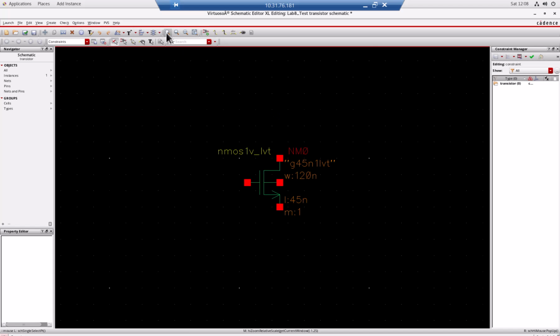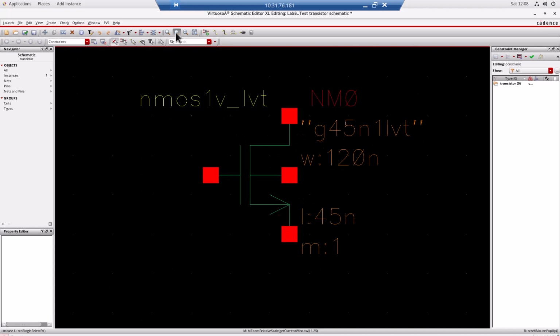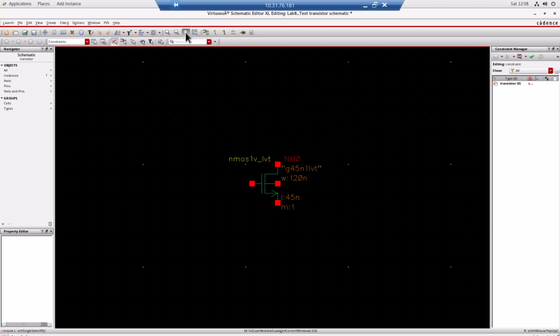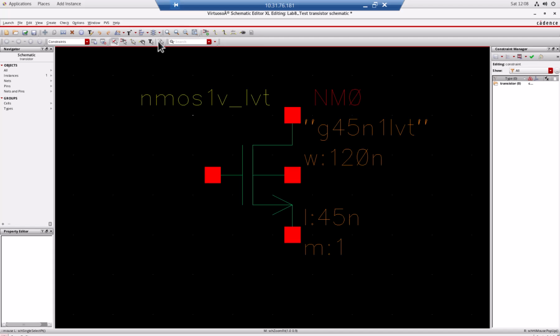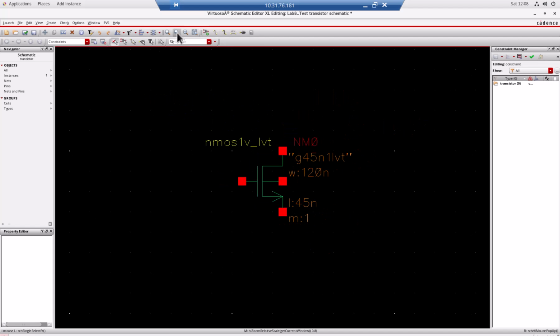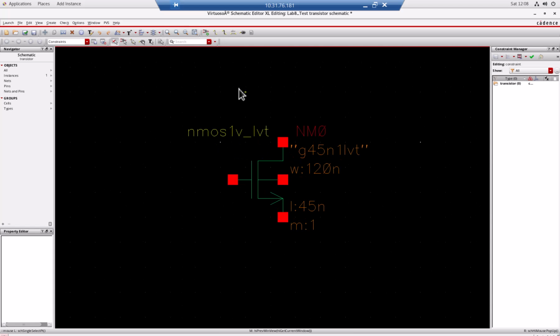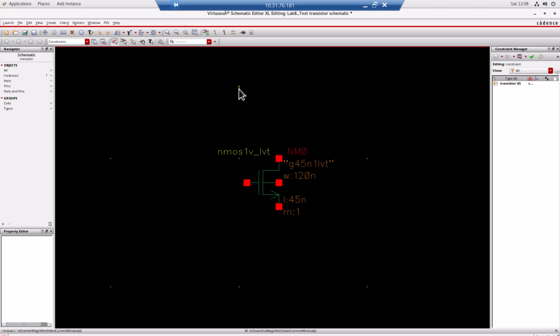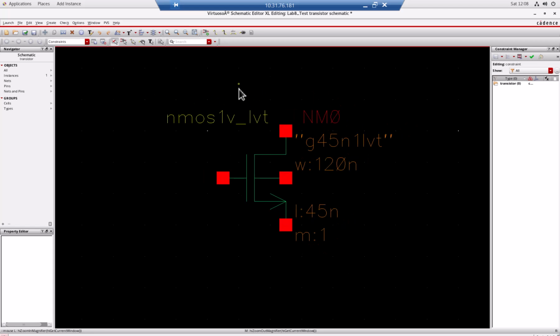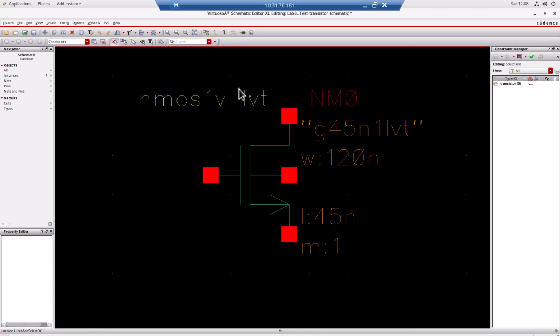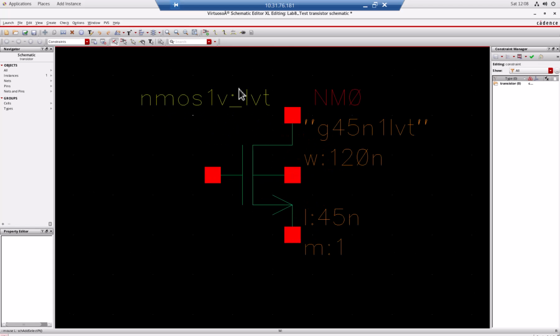You can definitely click the magnifying glass to zoom in or zoom out, right? Or zoom to fit, or zoom to a region. Now I can click this one to zoom out. But if you want to do the shortcut, just press the escape key. Make sure that the cursor becomes an arrow, and then you do Shift Z, right? Then it will zoom out. If you press Control Shift Z, then it will zoom out. And I say Shift Z is zoom in, right? Just play with it.